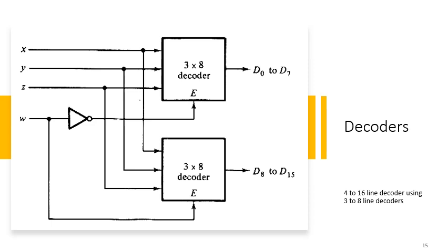So if you see the combinations that are being presented to the 4 to 16 line decoder, we've got the number of inputs that are 4. So the total number of combinations that are being represented at the output are 16. So those 4 lines are being converted to those 16 lines depending upon the conversion mechanism. So here we can see that W, X, Y, Z are the inputs.